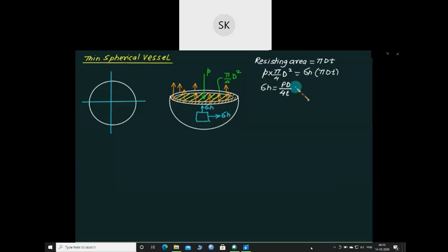And as per this notation, it is the same along the x-axis and the same along the y-axis. So sigma max will be equal to sigma min, and therefore tau max will be equal to 0. So there is no shear stress in this case, because tau max is defined as sigma max minus sigma min divided by 2.